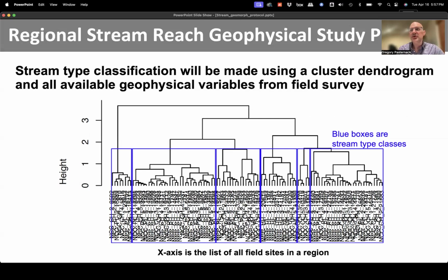Well, when you go to a site, you can take all the data and then you can turn it into site averaged variables like site scale, slope, width, riverbed height, bankfull height, active width height, valley height, entrenchment ratio, sinuosity. For each variable, there's a mean, a standard deviation, and a coefficient of variation, because they're measured at many cross sections.